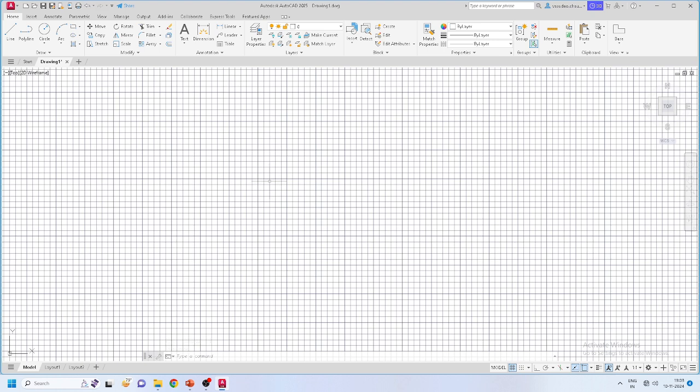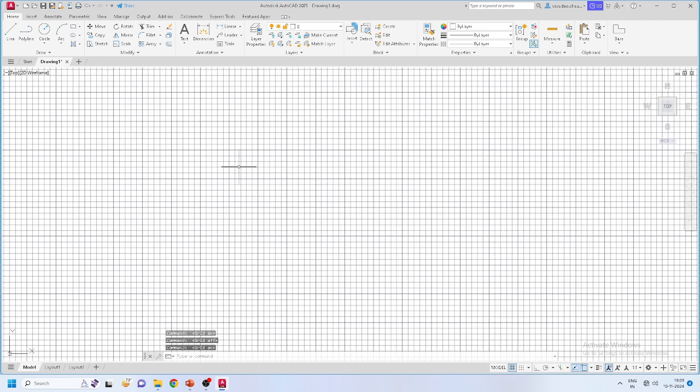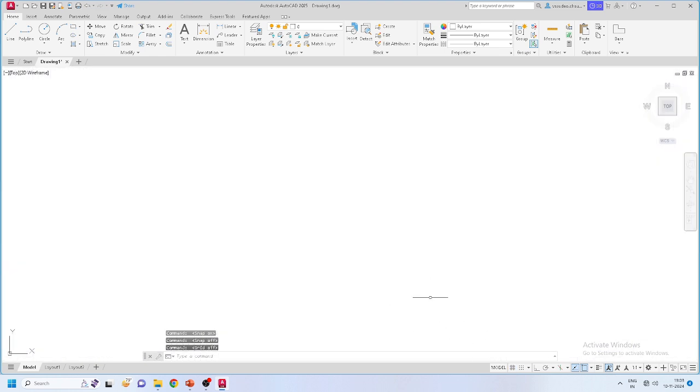Next, another important part is the grid lines, that may sometimes be useful, and sometimes we don't need them. So here in the status bar you can see that grid is on. If you click on it, it will disappear, right? So you can bring it back or make it disappear. And if you want to use this grid line and the grid points, then further you can snap to the grid points, you can turn it on and off, right? If snap is on, then only these grid points will be selected. I don't want both, so I'm closing them, right?